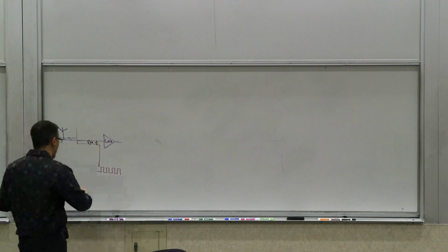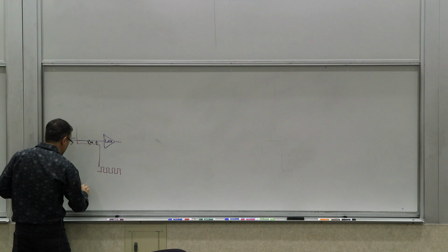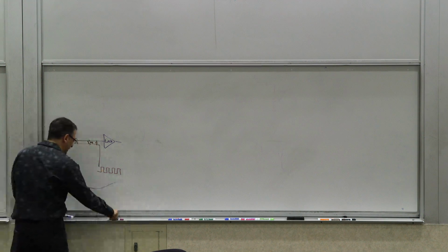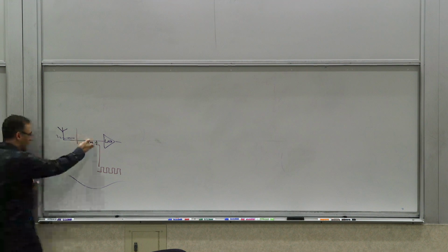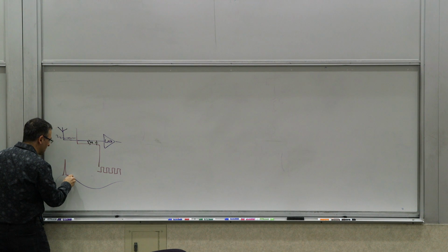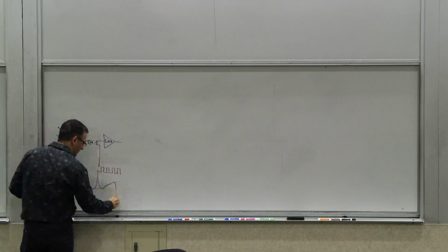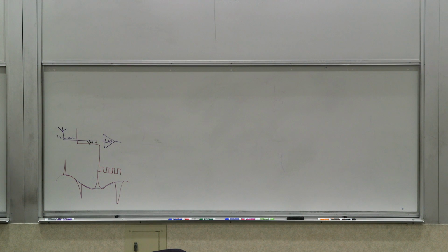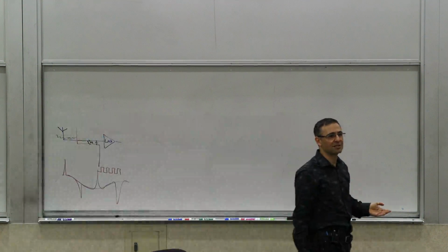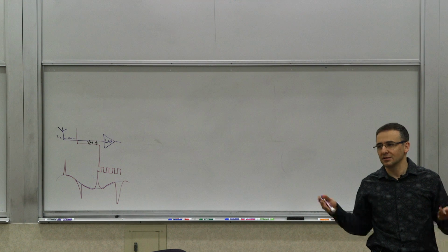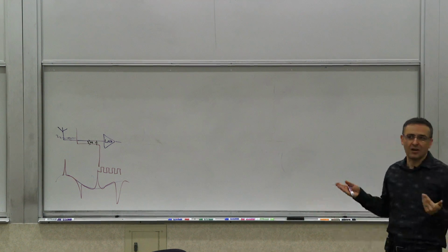What's going to happen to the signal? So you have this weak signal coming in. Let's say it looks like that, and then you have this big signal next to it. What is that going to do to your signal? You will see coupling, right? For example, if it's capacitive coupling, you will see spikes like that. Every time the clock edge switches, you will see something like that. And of course, this is not a highly desirable thing, because now your signal has this undesirable element on it. As you amplify it, this will get amplified, and it goes through the system, and it can saturate your system. It can create all sorts of noise and errors if it's digital, things of that sort, right? So this is obviously not a good scenario.